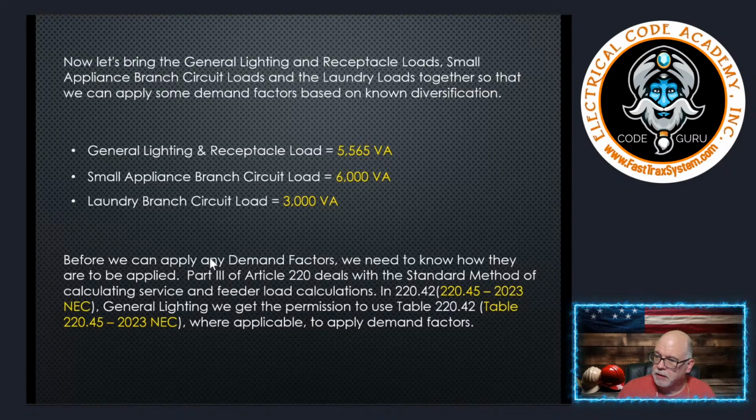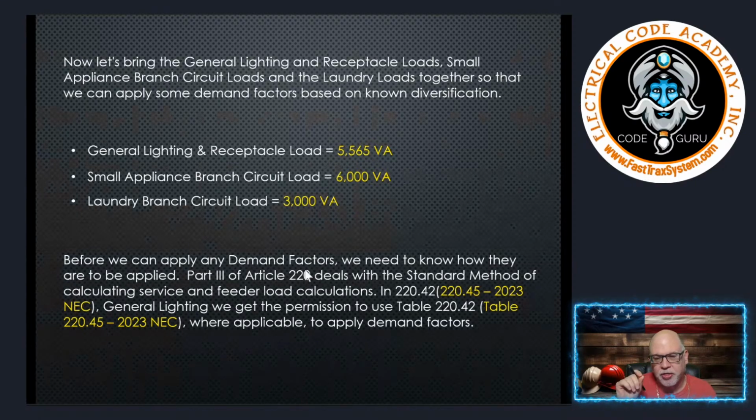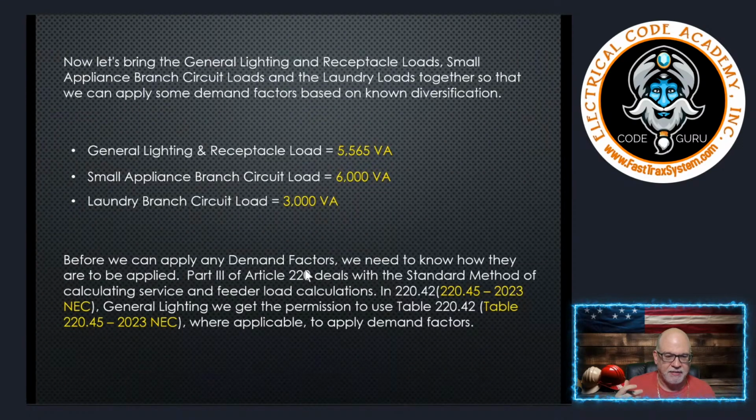Now, before we can apply any demand factors, we need to know how they are applied. Under Part 3, which we refer to as the standard method, it really doesn't call it that in the NEC. It's just the method, and it's Part 3, whereas Part 4 is the optional method.